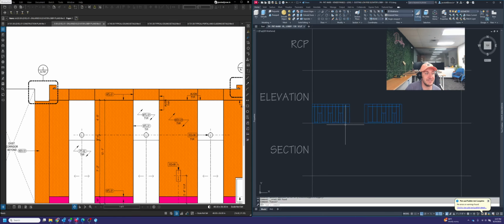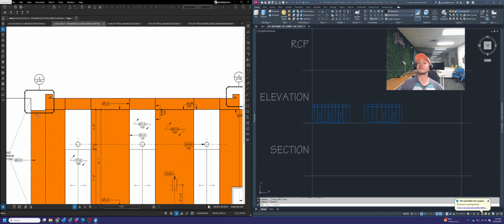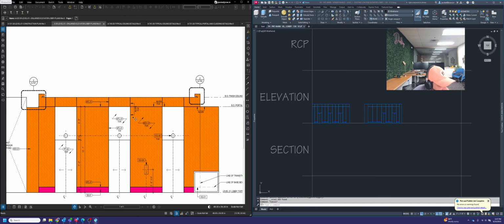And yeah, elevation view wise, the only thing left that we need to do before we dimension and tag and detail out some more of the information is I want to go ahead and figure this little ceiling detail out. This is going to be a little bit different. These panels will just go flat across to the ceiling, and there'll usually be like a little 3/4 reveal between the panel and the ceiling itself.